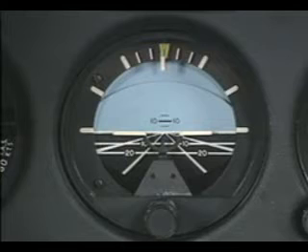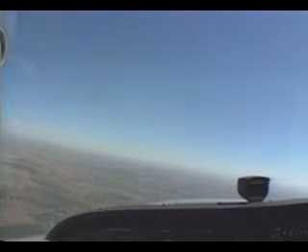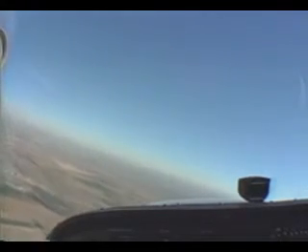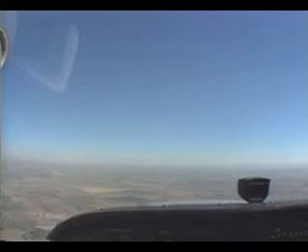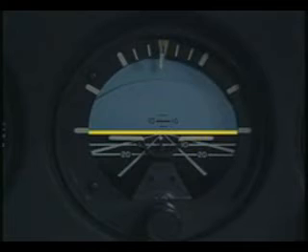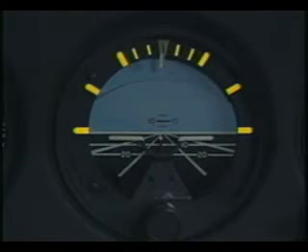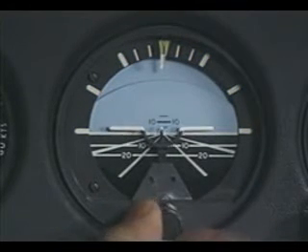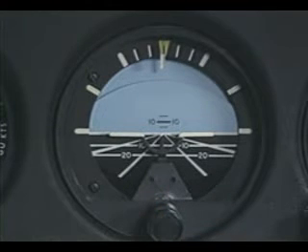Now let's take a closer look at the attitude indicator. This instrument senses rolling and pitching movements, providing you with a pictorial view of your airplane's attitude in relation to the natural horizon. The attitude indicator uses a miniature airplane and an artificial horizon to show both angle of bank and pitch. The artificial horizon is controlled by the spinning gyro. Index markings are incorporated to show you precisely how much pitch and bank you're using. An adjustment knob enables you to align the miniature airplane with the horizon bar before takeoff and during straight and level flight.